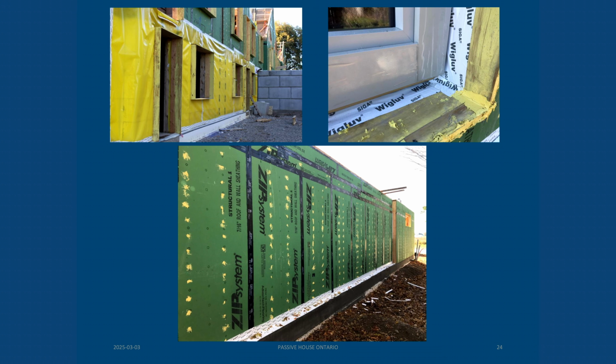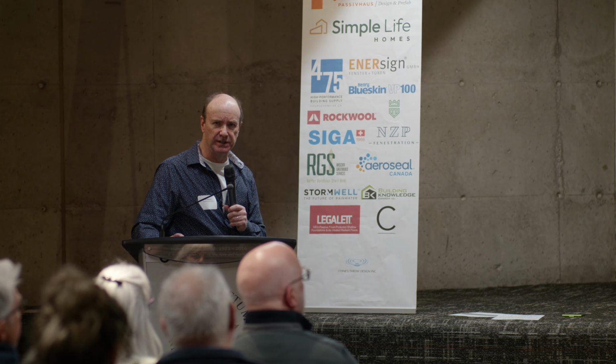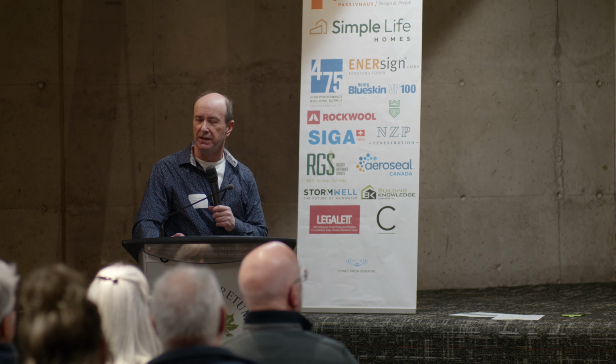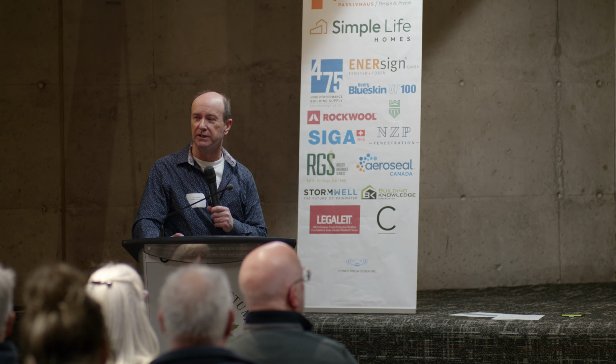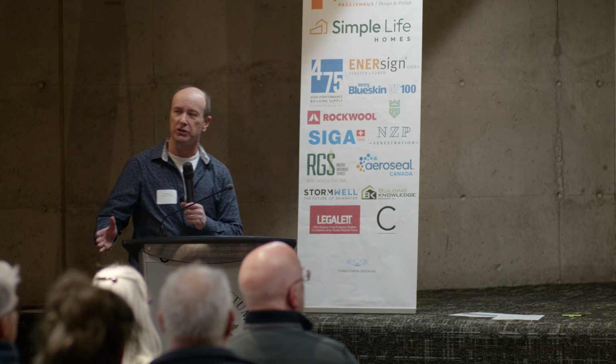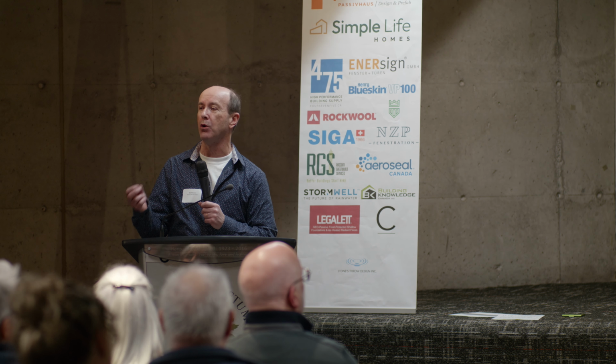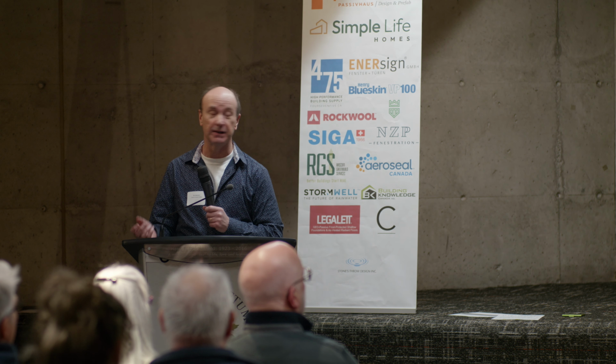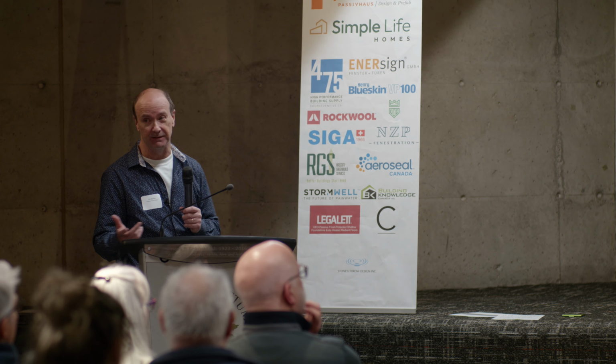This is the exterior of the ICF foundation wall with the membrane on it. Years ago, I attended some functions, and I think you were there, maybe it was even your project, but the best practice at the time was to put some sort of additional poly or membrane over an ICF foundation, as it was not as airtight as we all hoped it would be. Anyways, I've done it on several projects since, and it pays big dividends.